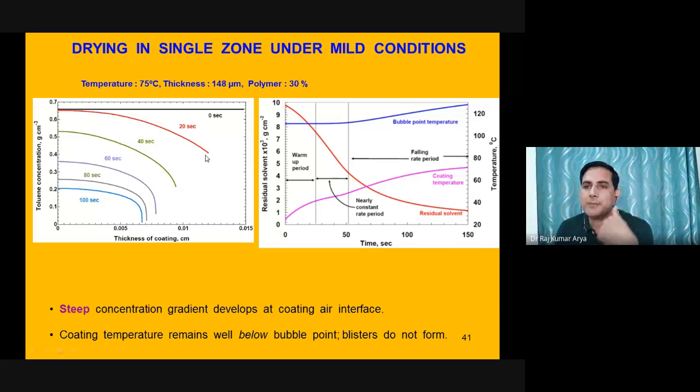So how can we capture it? Here there is no change. As I told you previously, we want to have unequal element size. Suppose we have taken an equal number of elements. Then we are just spending more computational time in this particular zone, where on the bottom side there is no variation in concentration. So I am wasting my computational power. I need to take care of that.